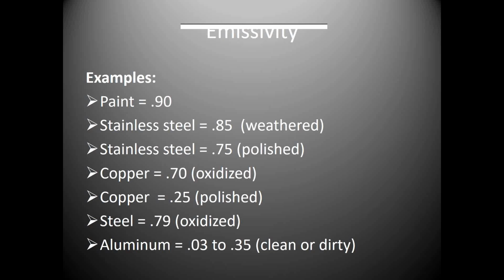Even if you pick up one of those little handheld temperature guns that many of us carry around the plant, if you look in the upper left-hand corner of that gun, there's a little symbol that says E equals 0.9. Just about every one of those is sold with the emissivity set at 0.9 as a standard, which means it'll read a painted surface, a solid wall surface, or a painted pipe surface.